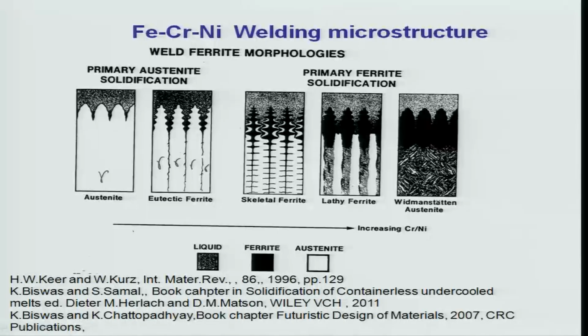So this is what is your, oh, I am sorry, this is not gamma, this is delta, okay. So this is delta, I should not make any mistakes. So these are actually delta iron, all of them are delta. And then delta plus liquid reacts and forms gamma. So you can see here, and this gamma then later on surrounds the delta, but delta remains retained, you cannot remove delta iron, correct.